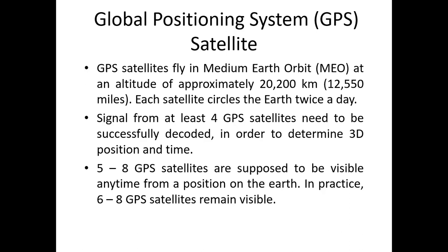From 4, 5, or 6 satellites, you are receiving signals, and they are located in different directions. So you need a very wide radiation pattern, meaning that the antenna gain of your receiver will be poor. So to ensure that you have sufficient signal power reception, the signal power level has to be pretty good.